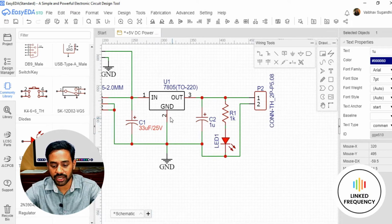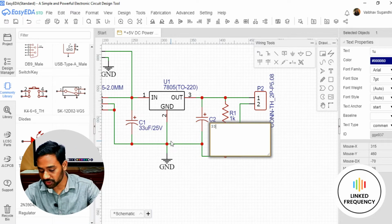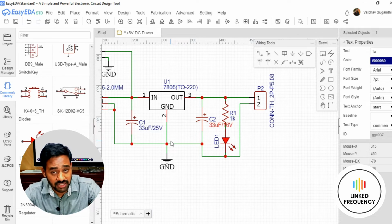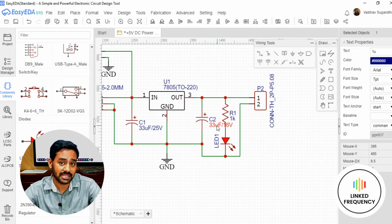Then at the output side, we will have 5 volt DC coming out from this particular regulator IC, which is the 7805. So that's why I'm going to use a 33 microfarad capacitor with 16 volt, because 10 volt is not available in industry on a larger scale. Probably it is available, but 16 volt is more common than 10 volt. That's why I'm going with 16 volt.